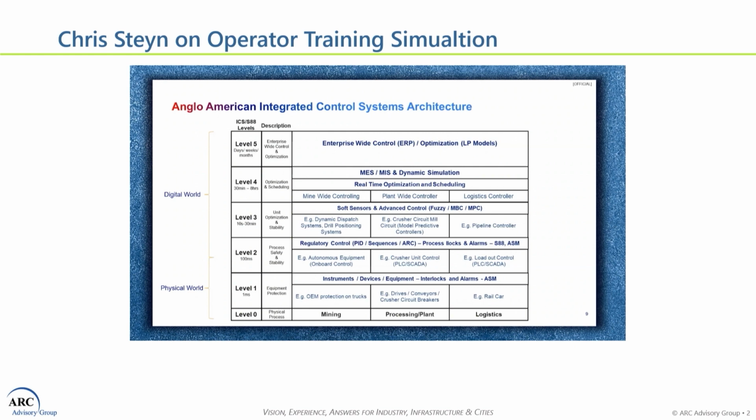Level 4, we've got plant-wide optimization, where we use the Honeywell DQP for that layer, and then on top of that we have a level 5, which is something we really are introducing to the plants lately. Of this entire hierarchy, you can immediately see, and it's mentioned on the left-hand side of the slide, that level 0, level 1, and level 2.1, if I may call it that, is actual physical hardware in the field. It's either pumps and pipes or drives or PLCs.